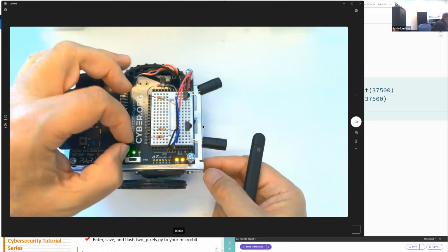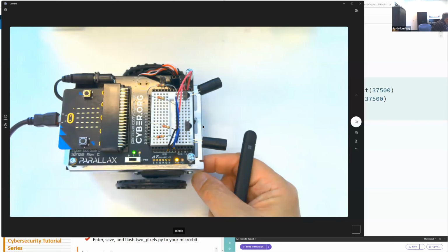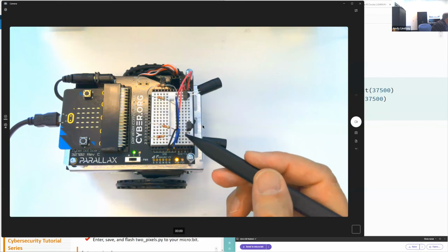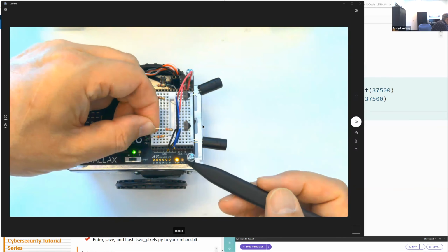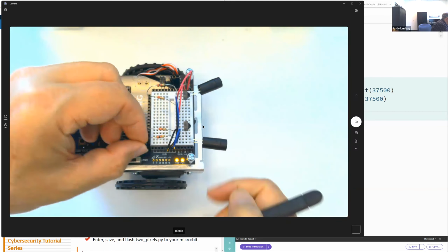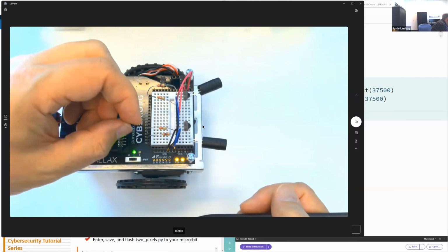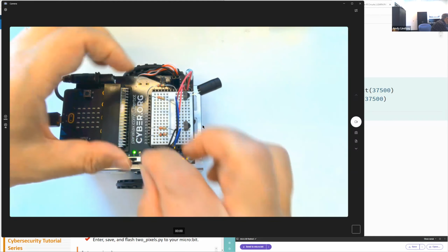Let's see. For example, if I float the resistor that goes from the bottommost pin to P2, the light stays off. No, if I float the P1 pin, it just stays on. So probably not the P1 pin.